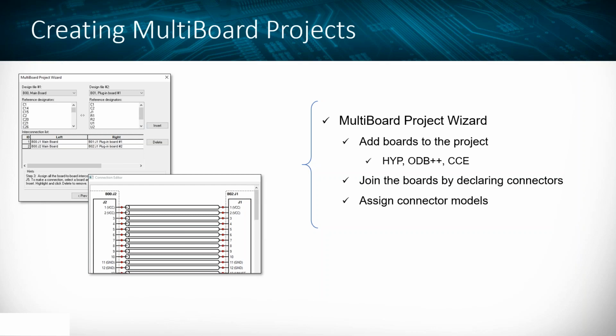So Mike Earp, I see that your question is, can a cable connection between boards be analyzed in aggregate analysis? Yes, definitely. We can insert an S parameter model or a SPICE model for use as our connector, and then use that in our simulation in order to provide the highest quality and closest to real world result that we can.